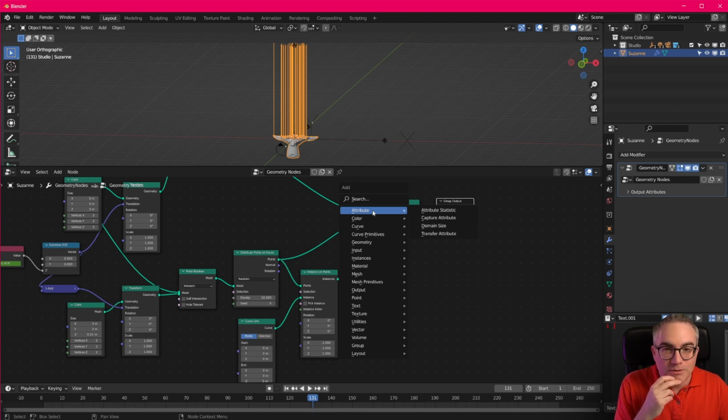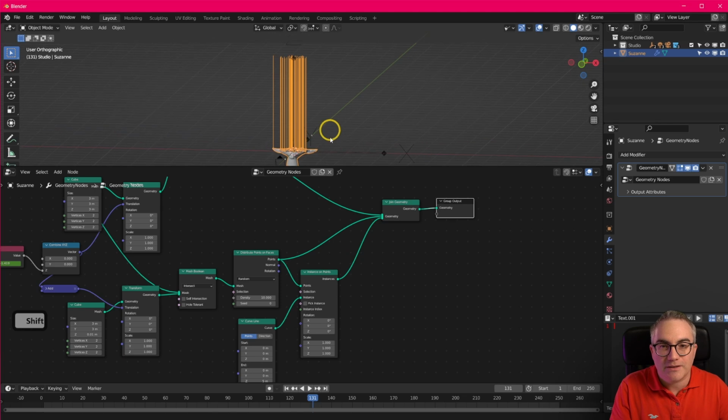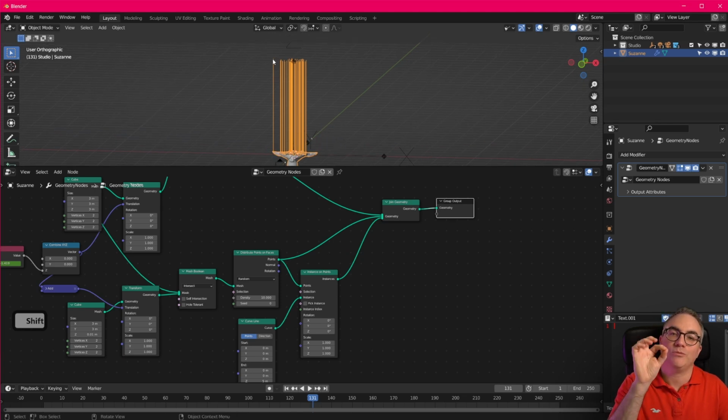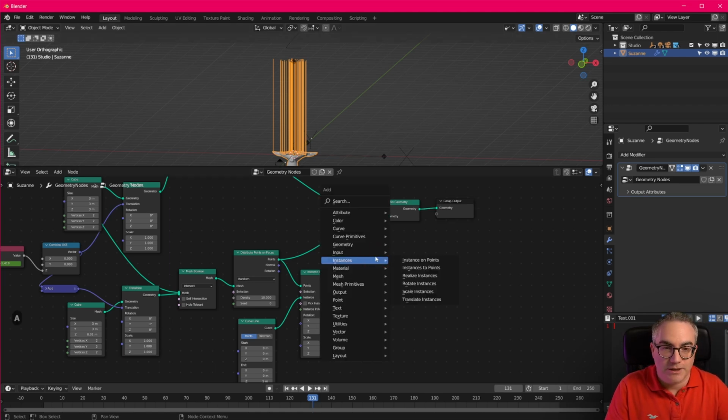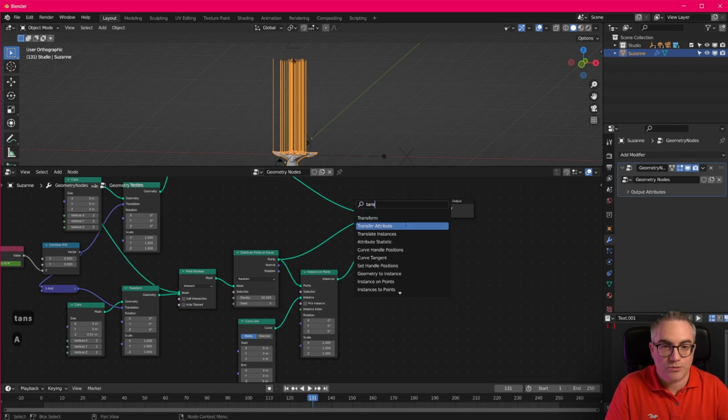So I wanted to move, right? This is a curve now, a line, and it has a start point and an end point. I wanted to move the end points to a single, like, absolute point on the top there. All of those lines should be basically emitting the laser from that single point. So I thought, well, you're gonna need a transform node.